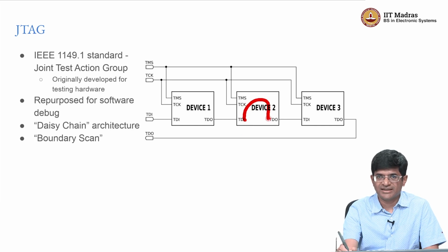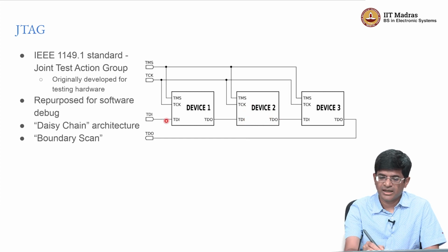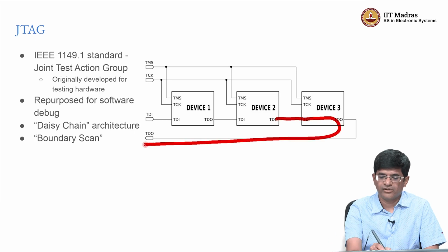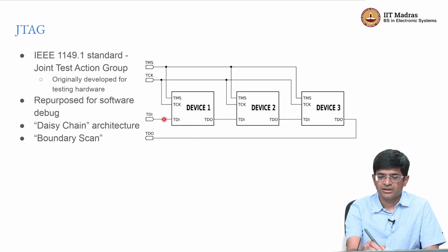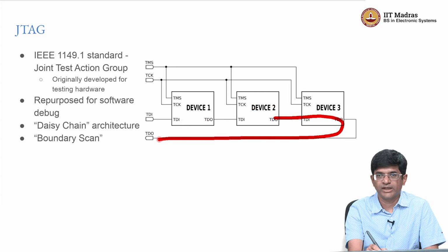There is some state corresponding to the internal registers. There is some combinational logic. Under those conditions, how does this behave? What will be the next state of each and every one of these registers? So you pulse the clock, capture all of those internally, and then you do the same thing. By again just pulsing TCK, I can now read out every one of those bits on TDO and get it all the way back to my host and say, okay, this is what I sent in, this is what happened when I pulsed the clock, this is what I got out as a result.